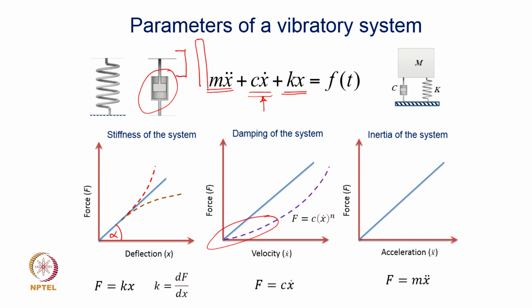We always approximate the damping, and it is really not necessary, from an engineering viewpoint, to get deeper and generate complex nonlinear governing equations for generating a more accurate solution. Most of the time we are vying for responses which are accurate from the engineering perspective. We are only interested in getting a quick, workable, practical solution of these vibratory systems, so a very accurate solution may not be relevant or important. So, from all practical viewpoints, damping is treated like C x dot, and C can be treated as constant. But I discussed these points so that you are aware that these are the underlying assumptions on the basis of which you are solving these equations, and as long as you know that these are the limitations of this model, it is fine.